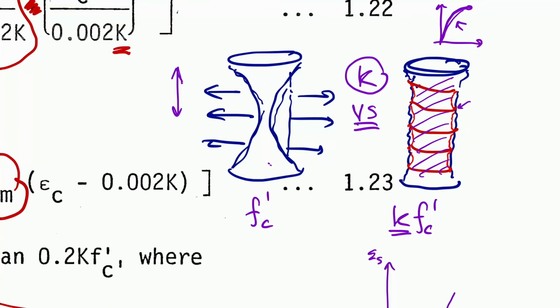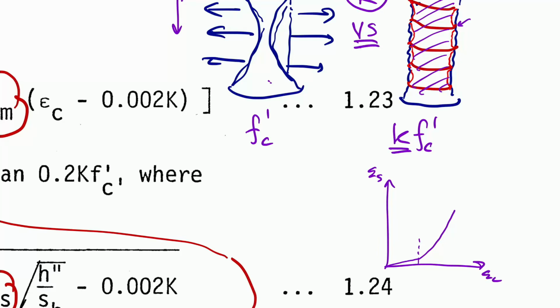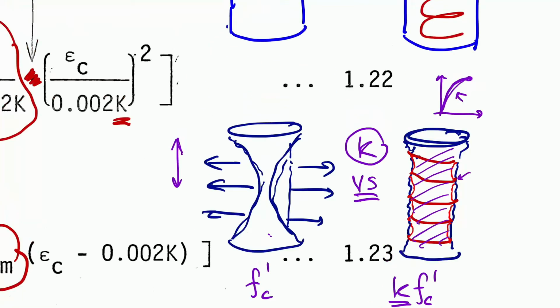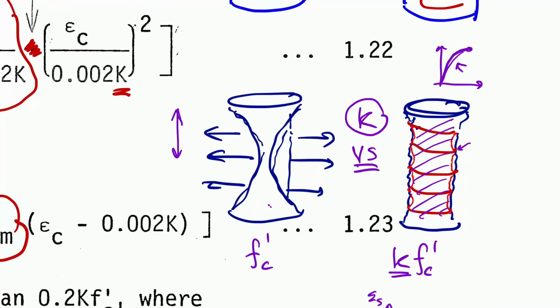But the thing is that since people feel the mobilization of epsilon s is not much in the initial part, in the original Park and Kent model they do not incorporate the effect of the steel before the ultimate capacity of concrete. So that's it, right? But I think this picture should explain well why you get the K. How does the K come in? All right?